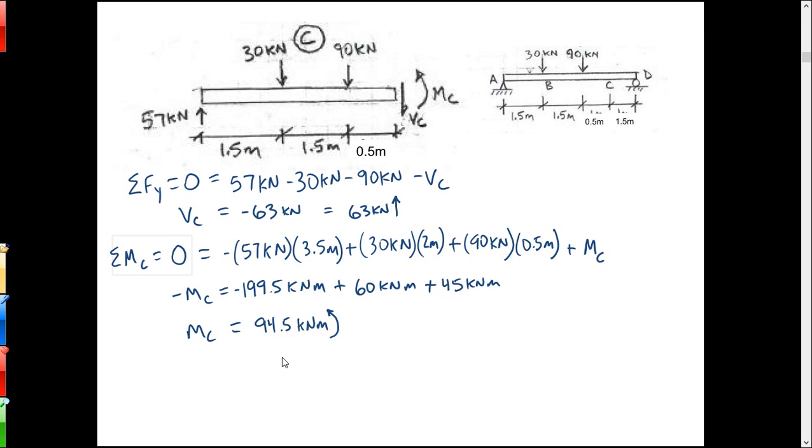And now the shear is kind of funny. The positive convention for shear is down, so you draw it down as you work from left to right. The convention on these things is to work from left to right. And then when you put it into the statics equation, the sum of Fy, it goes in as a negative because it points down. So we're kind of on the static sign convention when we do that. And then we could solve for it.